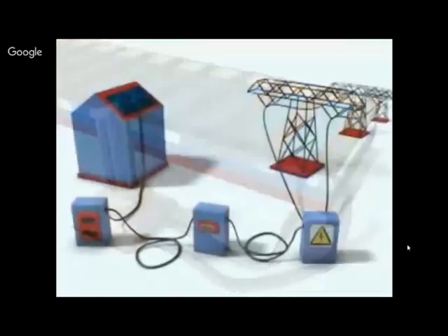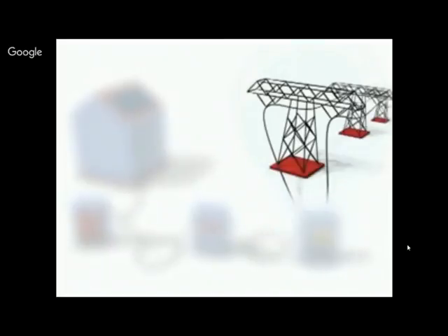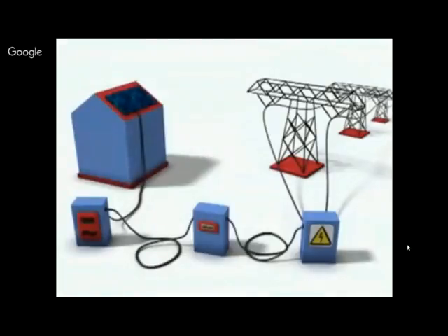Solar panels can be installed on the ground or on your roof. The solar cells collect the rays of the sun and convert solar radiation into direct current, which is eventually converted into more usable alternating current by a piece of equipment called an inverter. Connected to the inverter is another device that is going to measure the electricity produced by the photovoltaic system. Generated electricity may then be reimbursed by your electricity supplier.